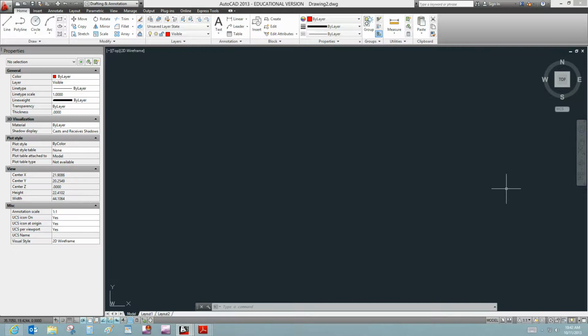You're given an outside diameter dimension of 73, but it should be a radius dimension of 73. So make note of that. My first step in this construction is to draw my outside diameter of 8. If your diameter will be twice 73, so your outside diameter will be 146. I just want to make sure that you get off on the right start here.